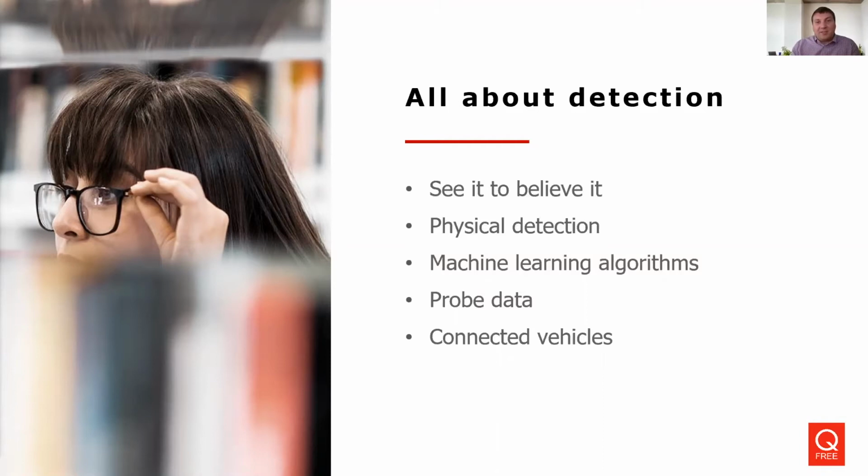Nowadays, there's at least one detection manufacturer I know of where a technician can stand by and say, hey, you can't see it, camera, but there's a car there, and push a button. And now essentially that has learned that that's what it looks like, and it automatically integrates it into the algorithm and distributes it out to all the detection equipment in the field. So there's a lot more modern detection out there to see what's going on.